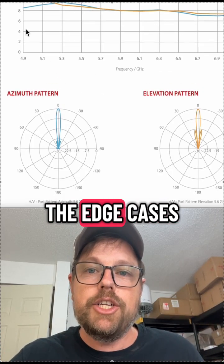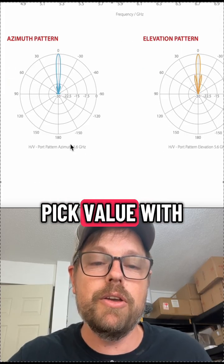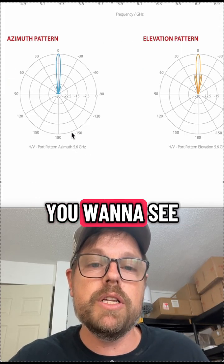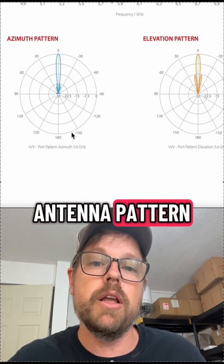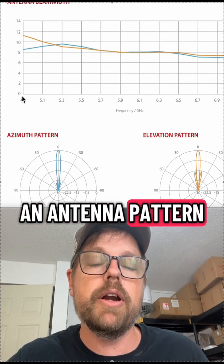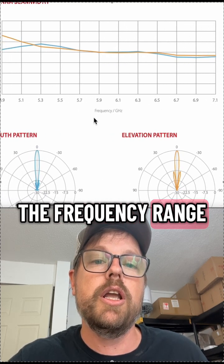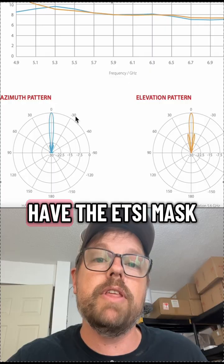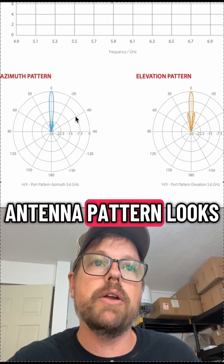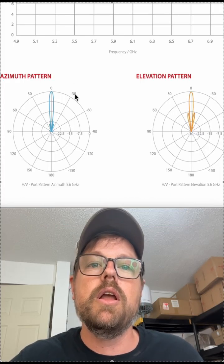You want to see the edge cases. You don't want to see a cherry-picked value with a hand-drawn antenna pattern. You want to see a detailed antenna pattern, and yet it is helpful to see an antenna pattern at the beginning of the frequency range, at the end of the frequency range, and then it is helpful to have the ETSI mask to let you know how that antenna pattern looks relative to industry standards.